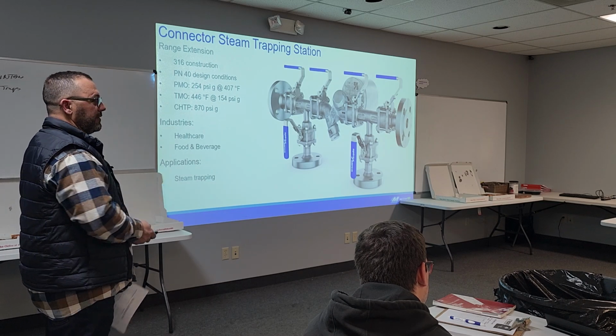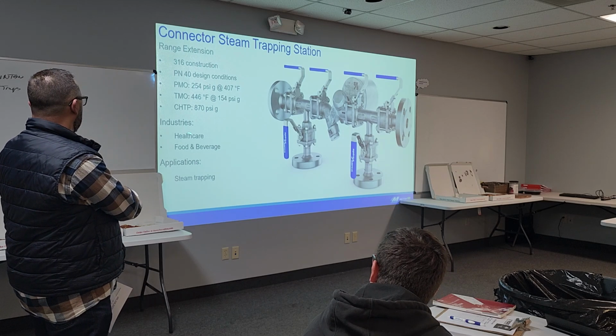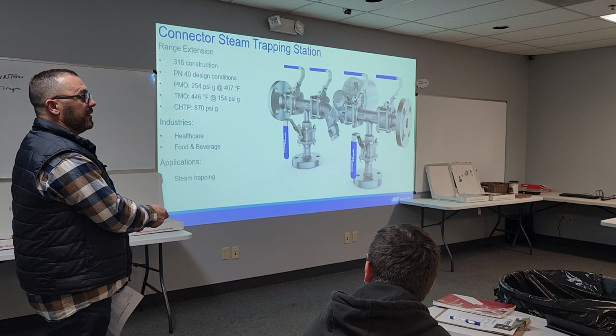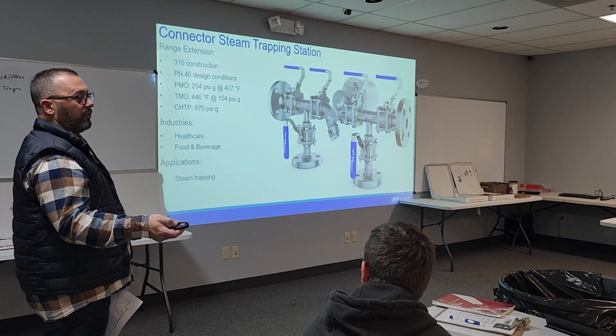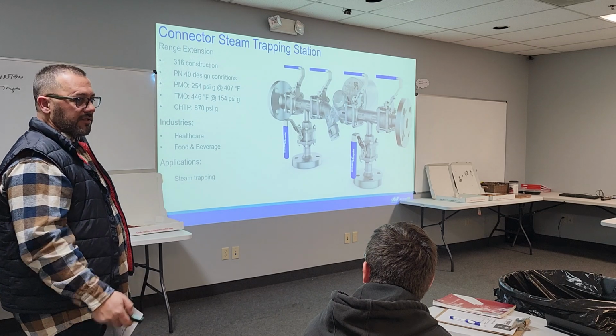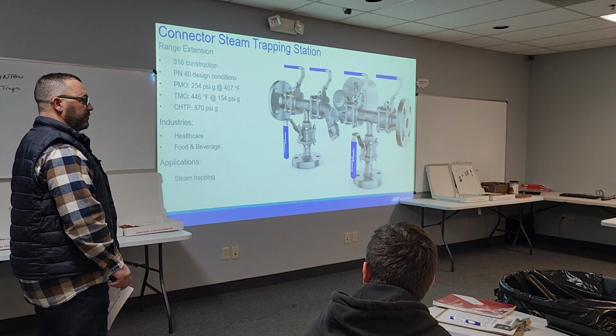Well, specifically, look right there. They're saying healthcare and food and beverage is the sweet spot for this. But I'm saying anytime, now, we don't want to do dissimilar metals, but on condensate return, anytime we can use stainless, it's advantageous for sure for the life.